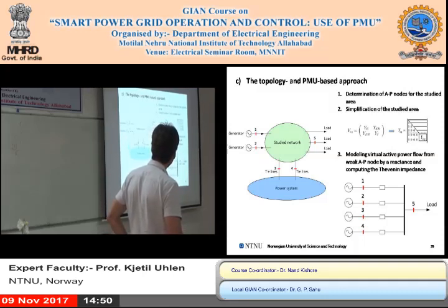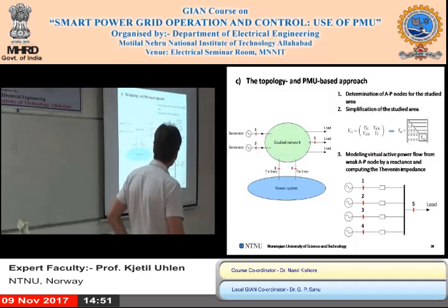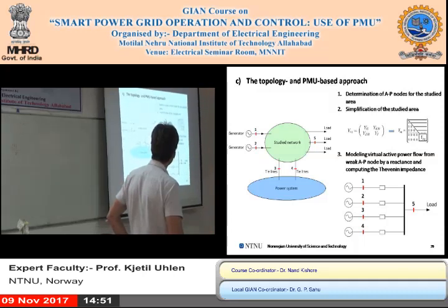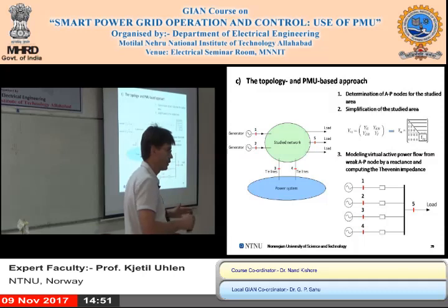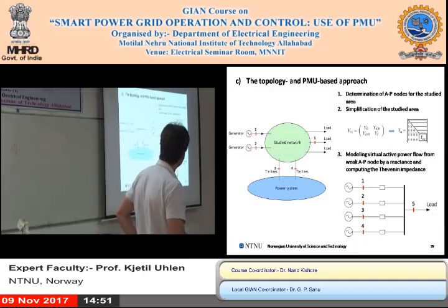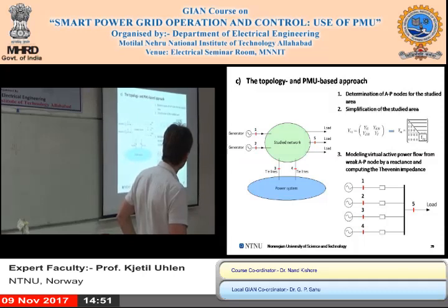If you now consider all these feeders, whether they are loads or generators, as injection to your system, you can formulate the admittance matrix as you would for any kind of network, and you could rearrange that by some kind of triangularization, so that you apparently have a system with several Thevenin equivalents feeding to the load.